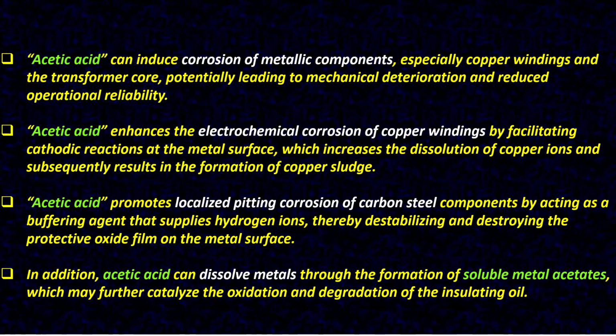Acetic acid can induce corrosion of metallic components, especially copper windings and transformer core, potentially leading to mechanical deterioration and reduced operational reliability.